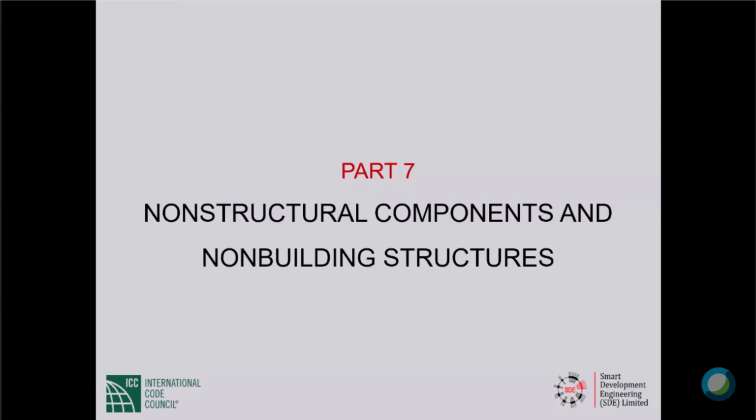Yeah, deflection limit. So deflection limits for roof members supporting plaster ceiling, roof members supporting non-plaster ceiling, and roof members not supporting ceiling. For floor members, the one number that is given is the same as for roof members supporting plaster ceiling. Yeah, so it is. I do not know what needs to be explained. So if it is a roof member not supporting a plaster ceiling, then we can tolerate more vertical deflection. That's all that the table is trying to tell you.